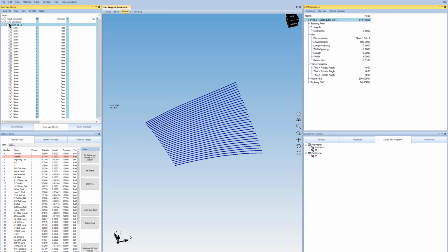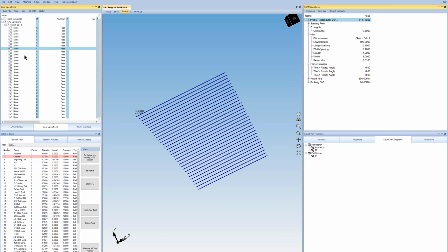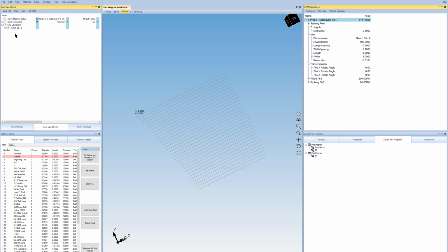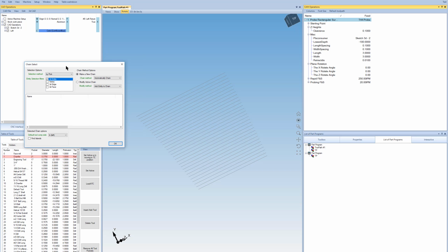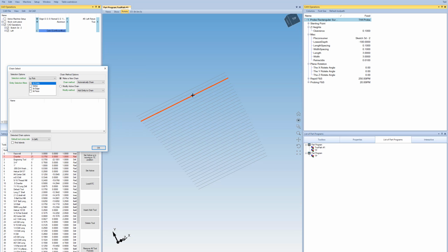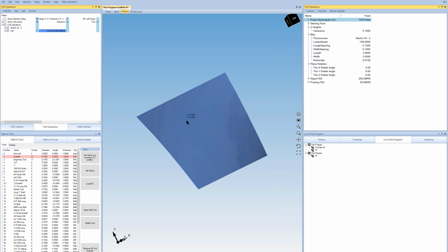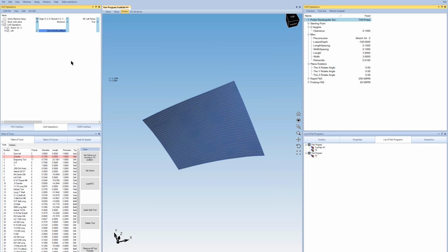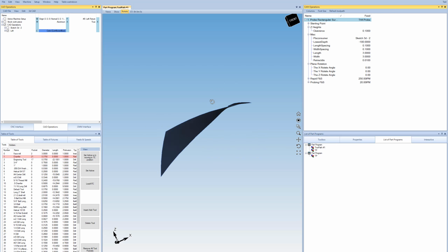So now we actually want to take these data points and make a surface out of it. So come over here to 3D CAD, and we do loft sketches into solid. Okay, and it's going to ask us what data we want to use for that. So we're just going to come over here and say pick by box. We could pick each one individually, but if you just pick by box, you can grab them all. And now we have a surface. We can turn off our sketch if we want, and there's our surface.